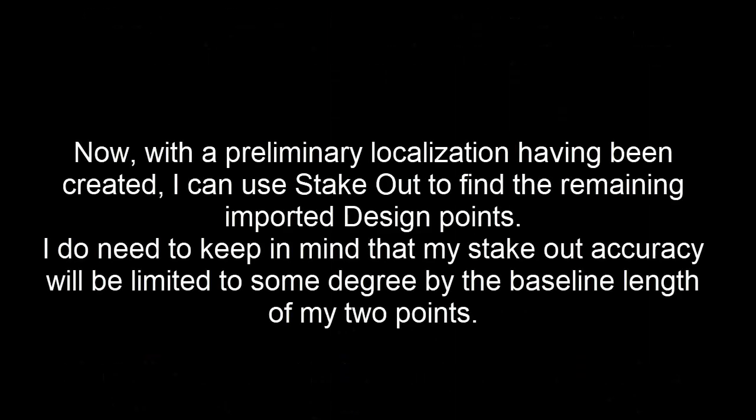Now, with a preliminary localization having been created, I can use stakeout to find the remaining imported design points. I do need to keep in mind that my stakeout accuracy will be limited to some degree by the baseline length of my 2 points.